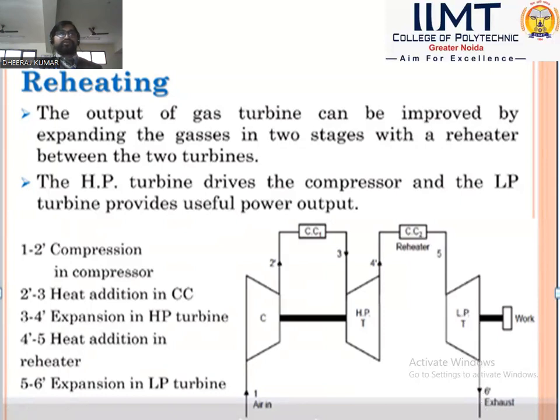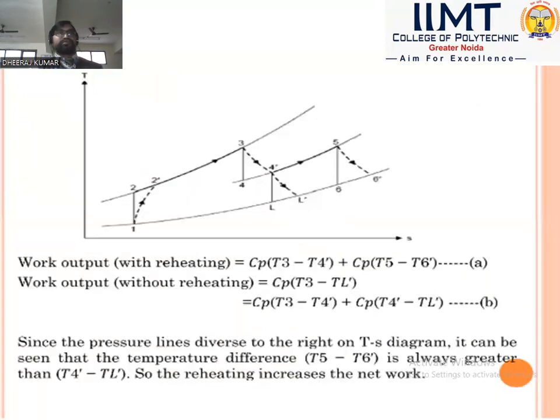This is the reheating process. During the reheating process, the work output increases. During intercooling, work input decreases. When providing reheating, the work output increases.